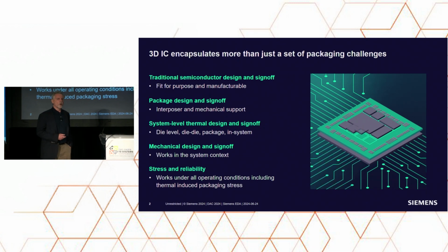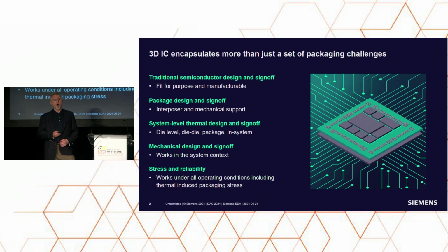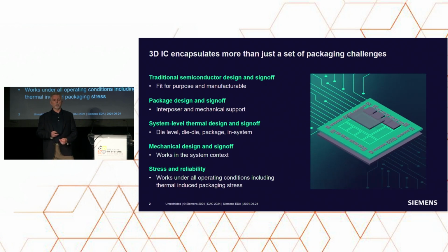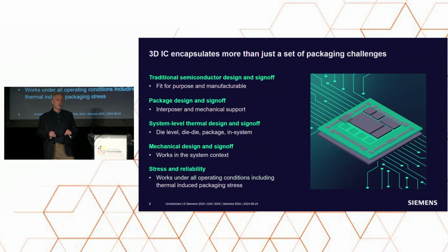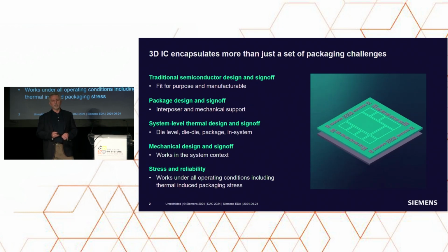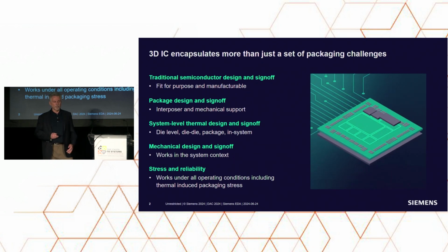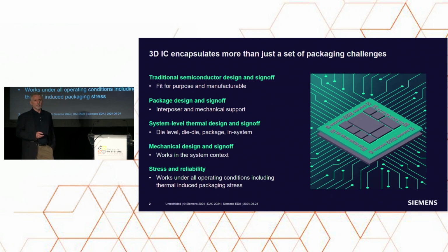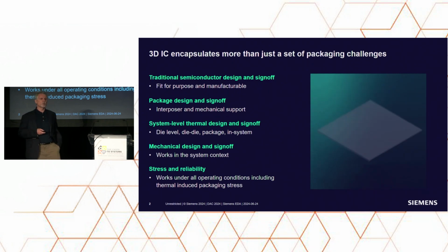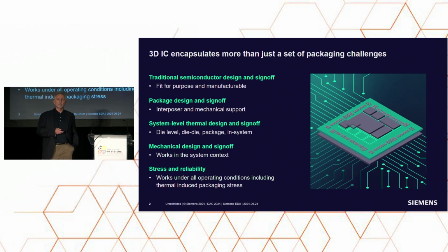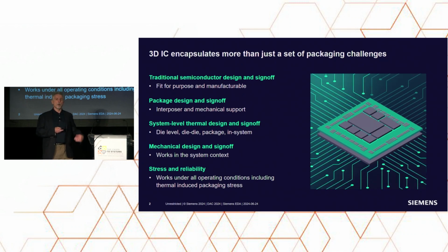So I always like to start these talks with defining a chiplet. Everyone talks about chiplets. A chiplet is an IC, an integrated circuit, that's been designed and optimized to be integrated into a package. Traditional homogeneous ICs are a single chip in one package. Heterogeneous is multiple chips in one package. Heterogeneous design, package design, 3D IC, those are all terms that talk about putting multiple chips in a package. It is a very different approach from the traditional IC design process and packaging.